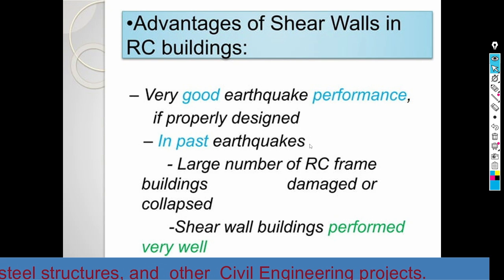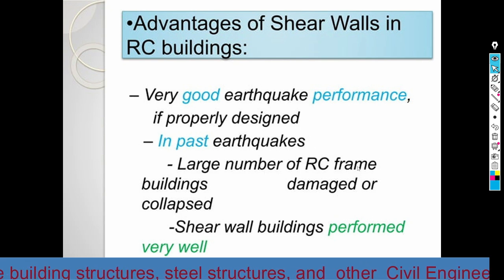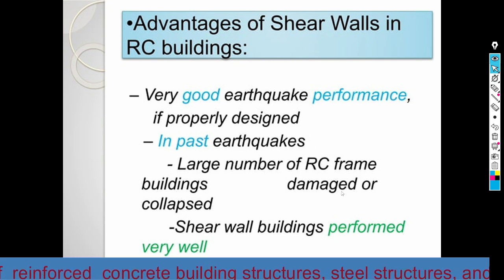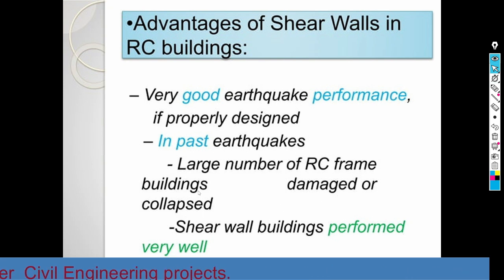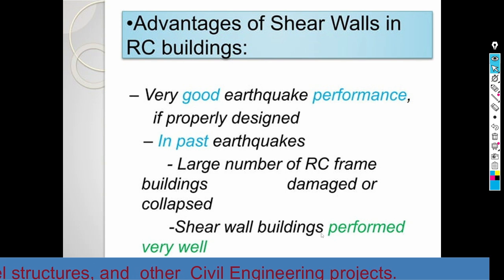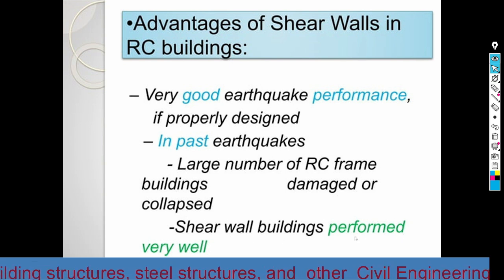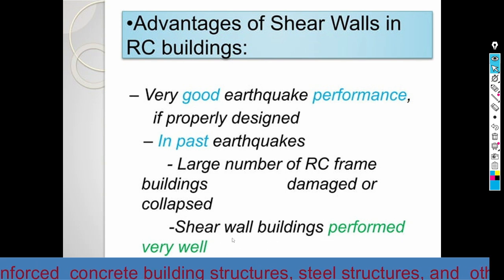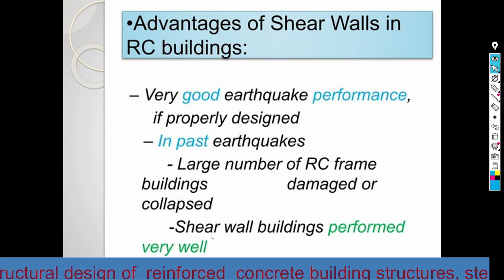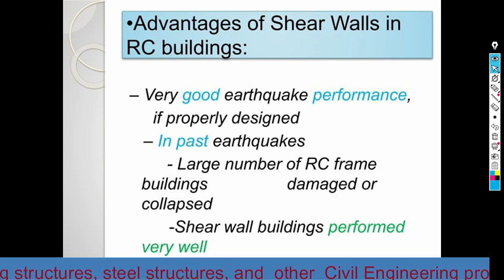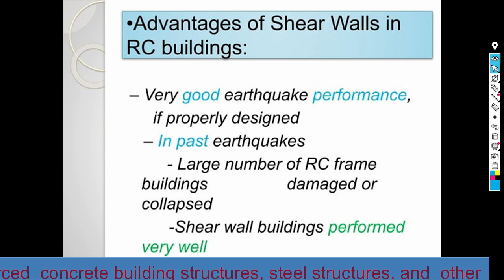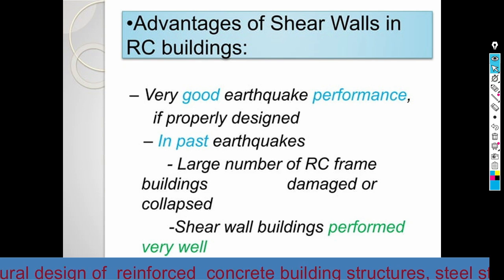In past earthquakes, a large number of RC framed buildings were damaged or collapsed because of the absence of shear walls. Shear wall buildings performed very well. So basically, whenever there is a large number of stories in a reinforced concrete structure, it is preferable to use shear walls.